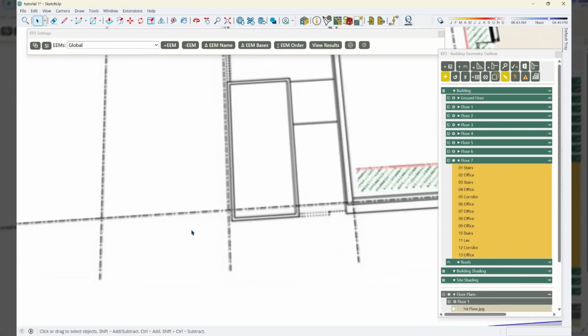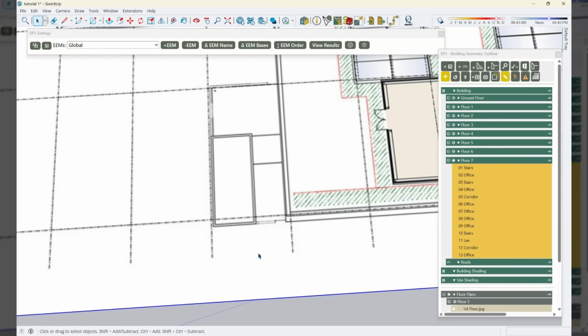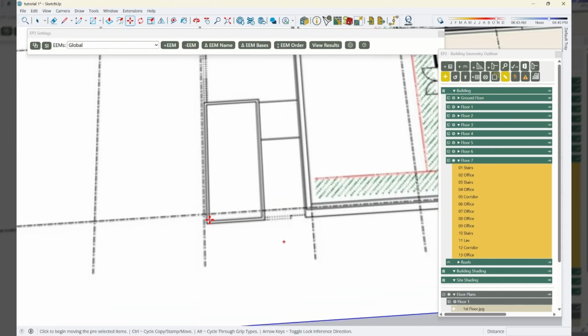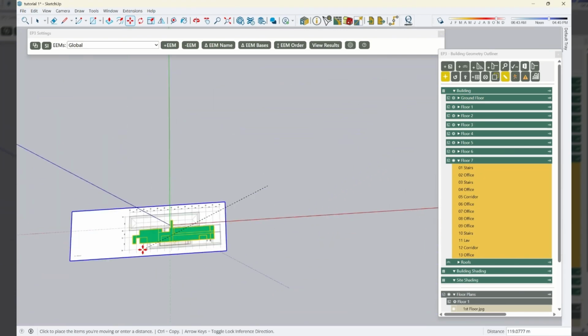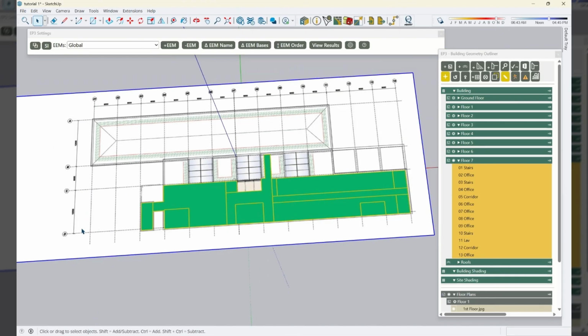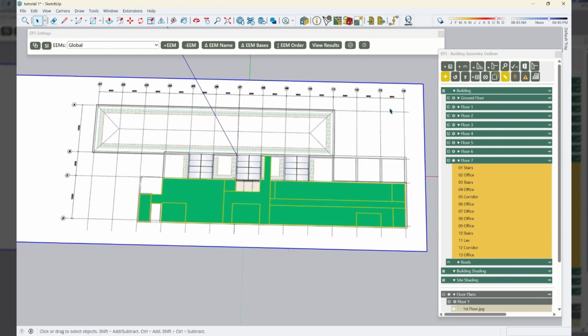Then we position it. And now the stairway doesn't exist on this level, but they've been quite kind and given us the outline. So that makes it quite easy for us to position this drawing and line it up with our other drawings. You may also want to choose, say, a grid point as your place to orient your drawings. That might be simpler instead of choosing a wall location, because that can maybe disappear as you go up a very tall building. So now I'll right click and say set floor plan and select floor 7.